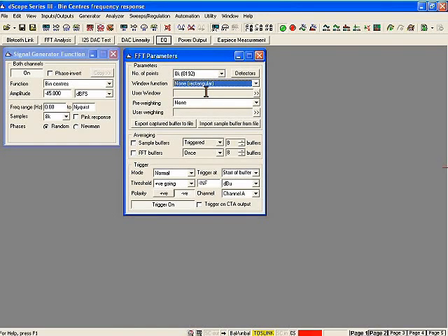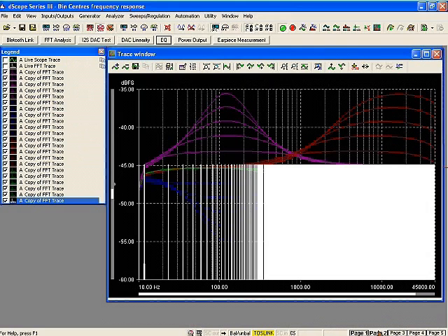This is a very fast measurement in comparison, and allows us to measure all of our tone components at the same time by plotting an FFT and, in simple terms, joining the dots to give us a frequency response. So let's look at that. Well, I have previously made a measurement using a very large FFT size.